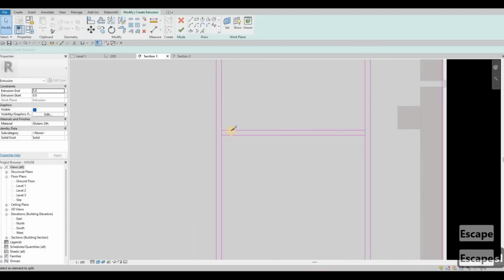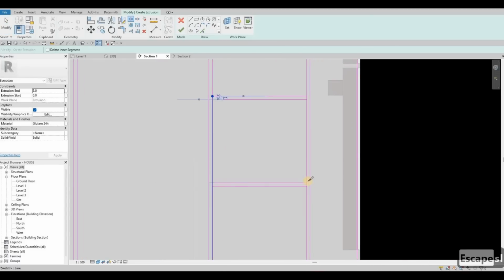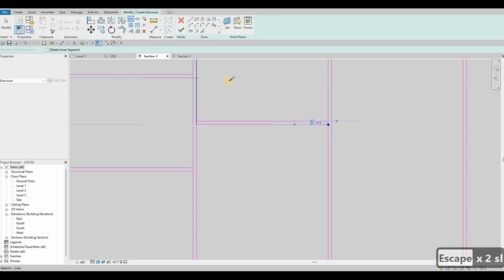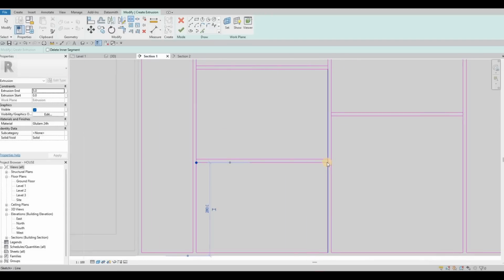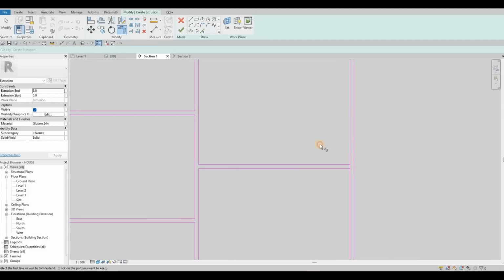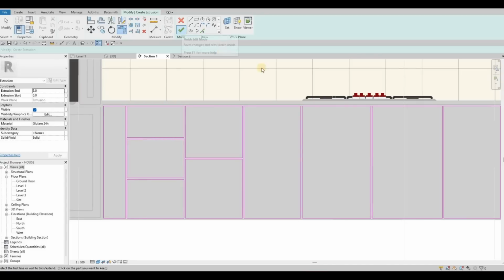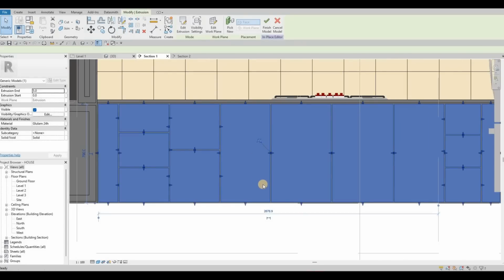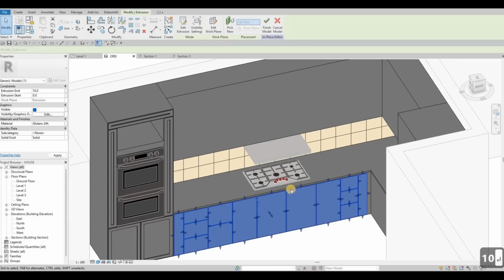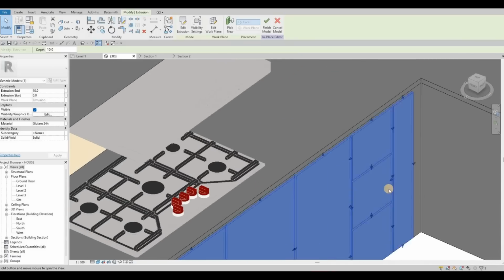And then SL to give them the cut there, and then we could just clean it up. So everything will be efficient, and then you're cutting everything correctly. And then TR, trim and extend. There we go. Now we could just click on finish so that we know everything is done properly. It's not done yet. We could change it to 10 and then offset this one with a void so that it's easier as well. So we have that one there.